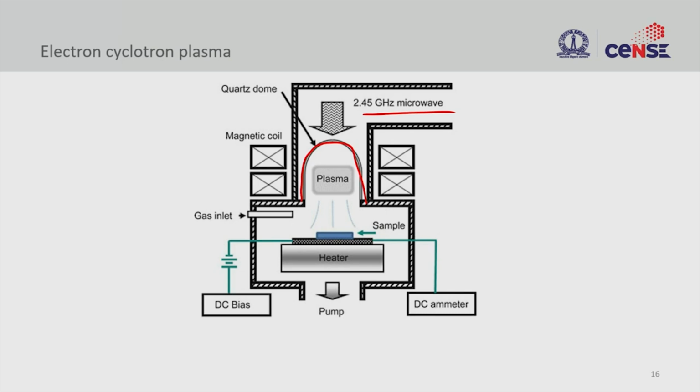The microwave creates the required energy here in order to create the plasma, and the rest is pulled through the pressure difference, and the DC bias that we apply. Unlike the other configuration that we saw, ICP, here we use a DC instead of an RF feed. And this is also used in some of the R&D developments, and also some industrial processes as well.